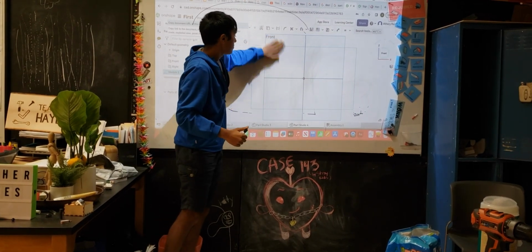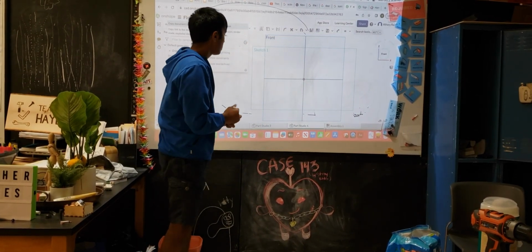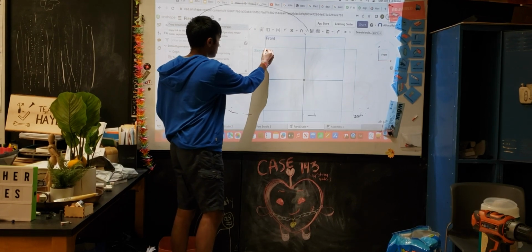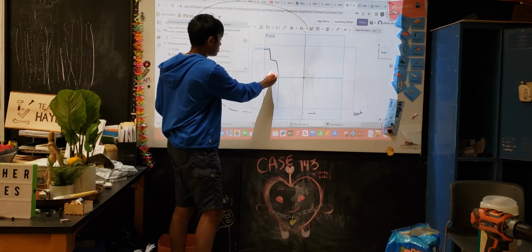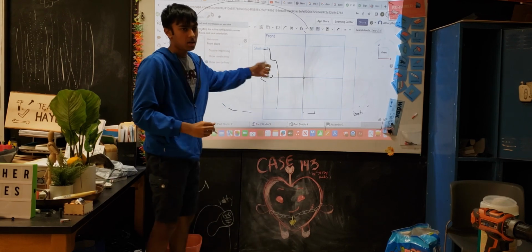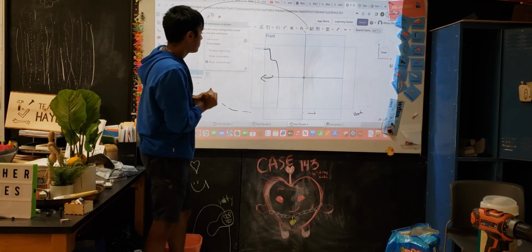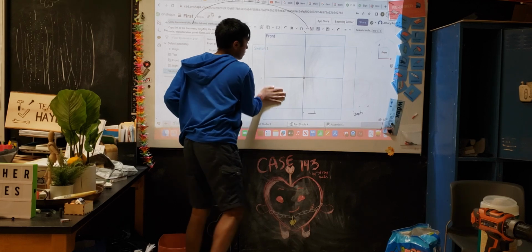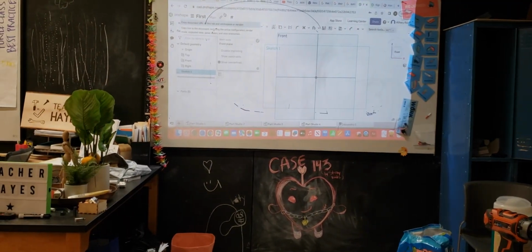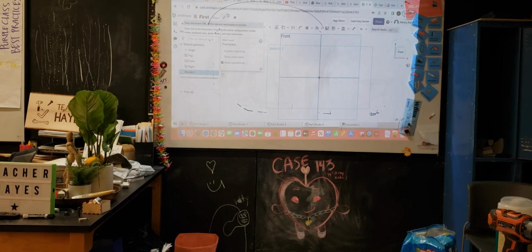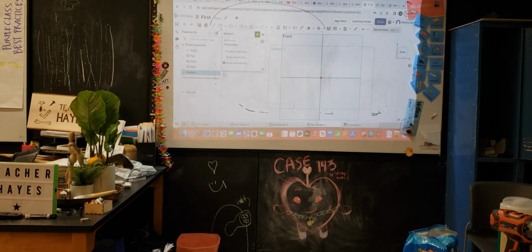So instead of making a circle and extruding, what we're gonna do is make a side profile for the spacer, and then use the revolve tool to complete the cylinder. You can somewhat imagine that. We'll go over it on Onshape right now. All right. So this is some high level stuff right here. Yeah, spacer making is crucial.